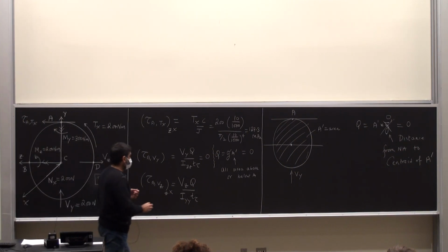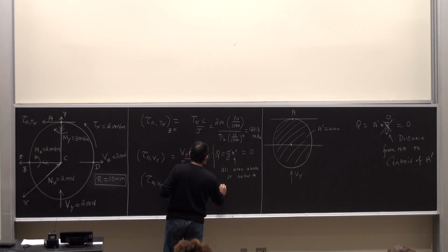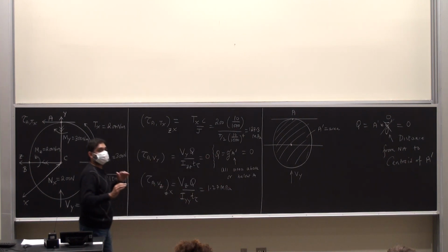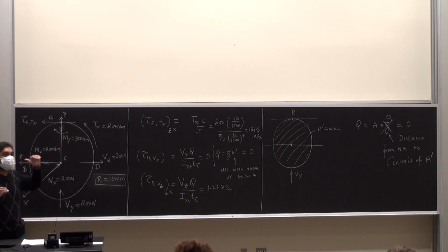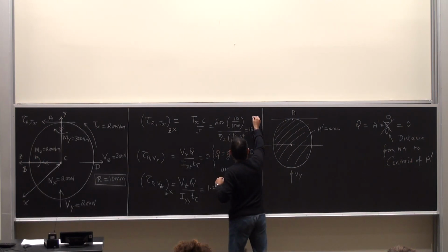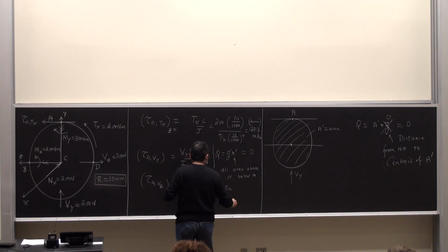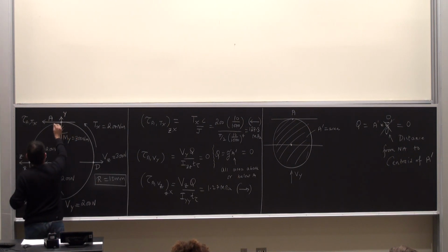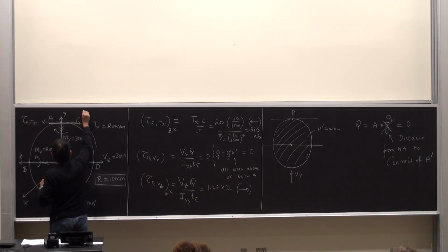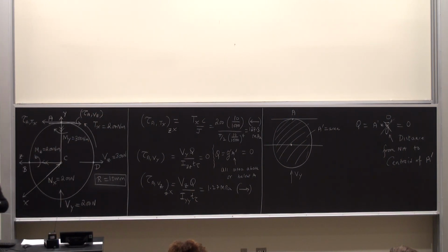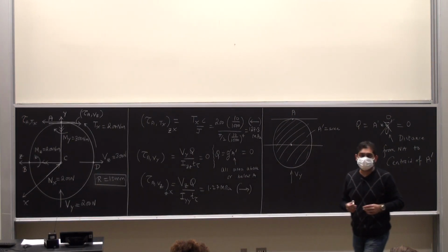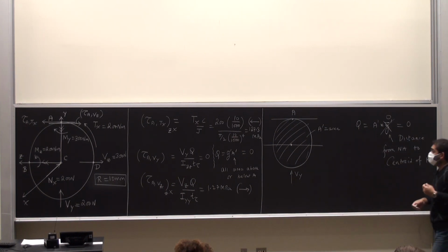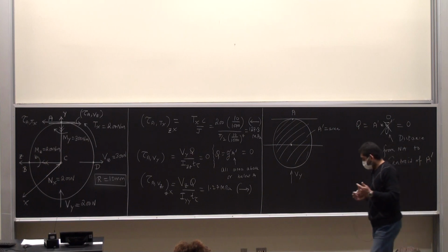After we did the calculation, this was 1.27 megapascals, but this was pointing to the right because this has to track the direction of the shear force. This was pointing to the left. This was pointing to the right. So if you want, you can draw a figure here saying tau A due to Vz. They are at loggerheads with each other, which means that we have to subtract one from the other, depending on whatever you want to call as a positive or the negative, but I don't like saying positive and negative, so we write it out this way.